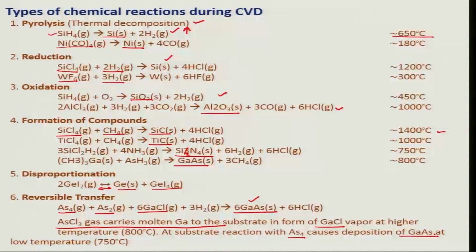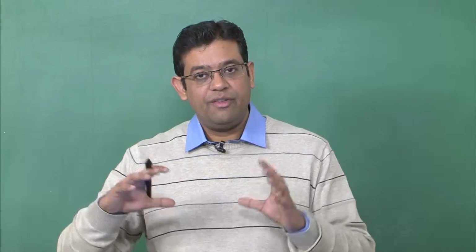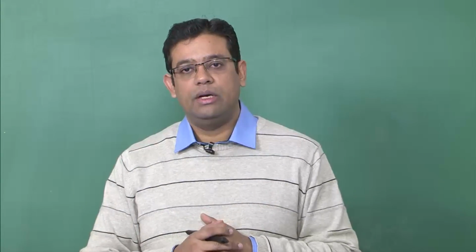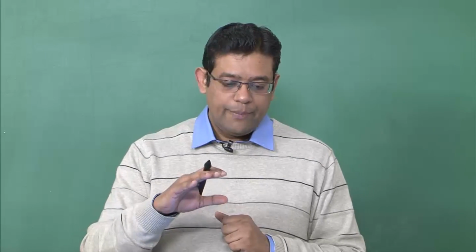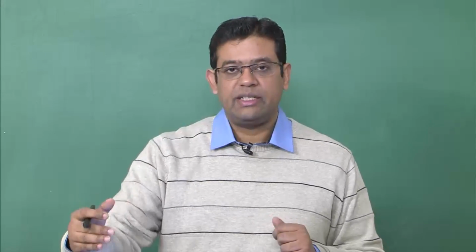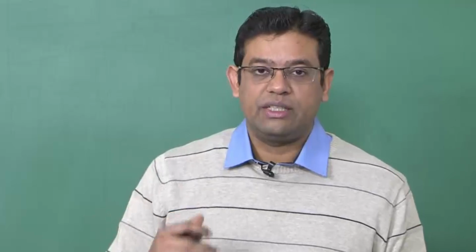So, these are various types of reactions which might happen, and there might be some more. Why we are discussing this is because we have to keep the reaction thermodynamics in mind when we design our thin film deposition process, and we need to adjust the temperature according to reaction thermodynamics.